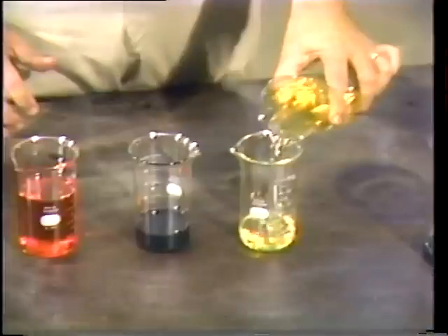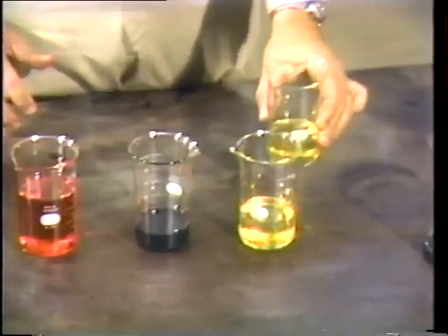The thinner the fluid, the lower its viscosity. Choosing a lubricant with the right viscosity is important because a lubricant that is too thin will not work properly, while one that is too thick will cause too much fluid friction. Viscosity is related to fluid friction. A liquid with high viscosity will produce more fluid friction than a liquid with low viscosity. Too much fluid friction causes overheating and makes it harder to start a machine.